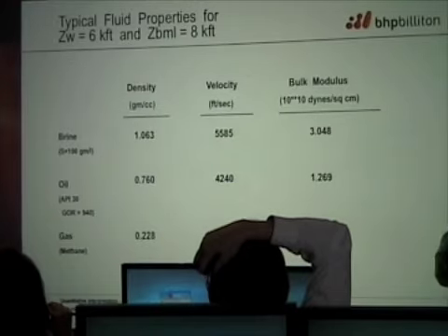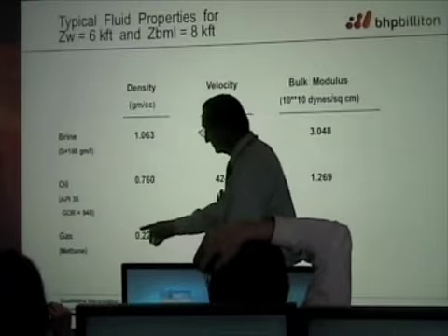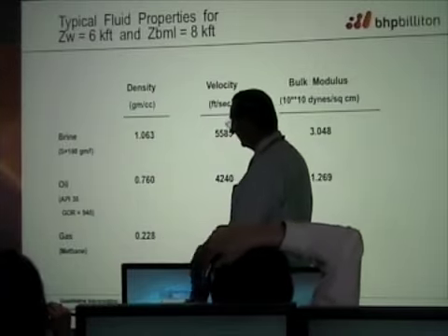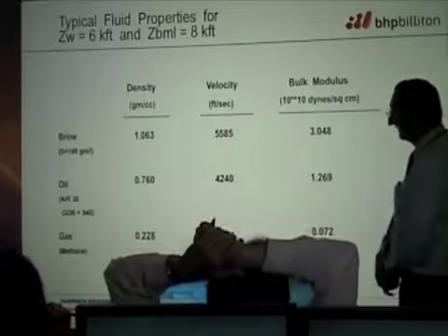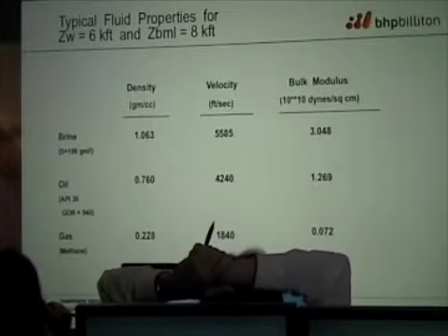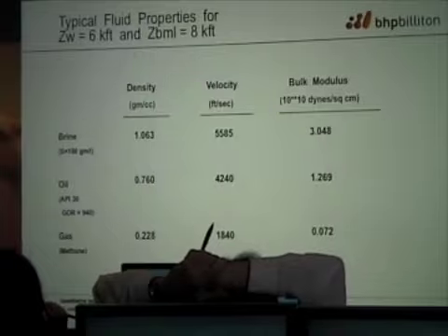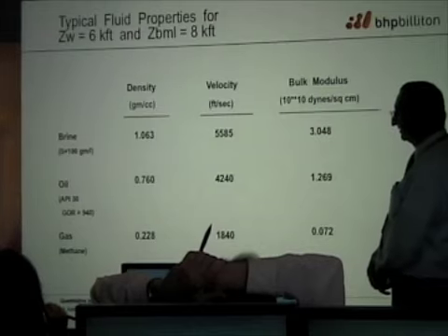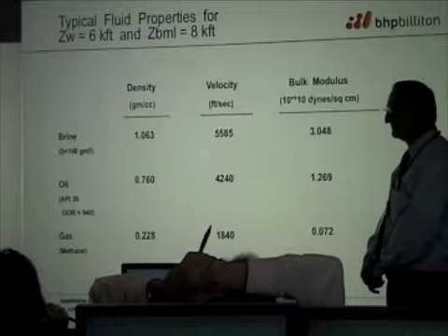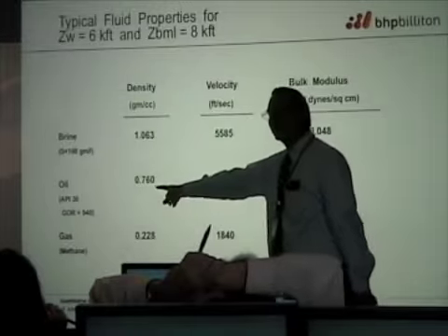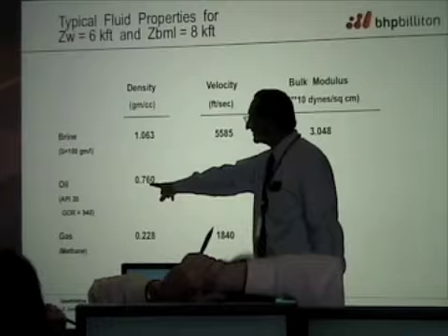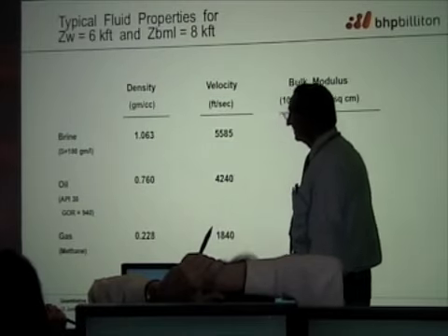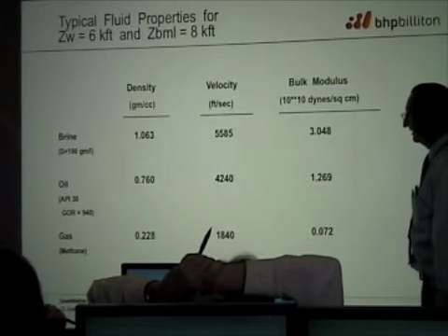For oil, 30-degree gravity oil, with a gas-oil ratio of 940 cubic feet per barrel. Don't you love that term, cubic feet per barrel? I'm not sure whose bright idea that was, but anyhow, if it helps you, there's 5.6 cubic feet in a barrel. This is the density of such an oil.